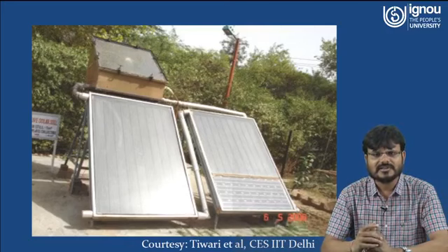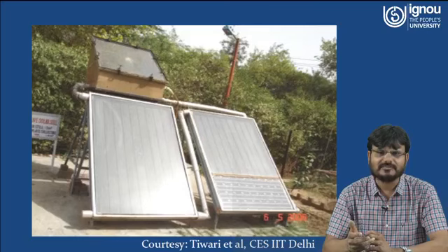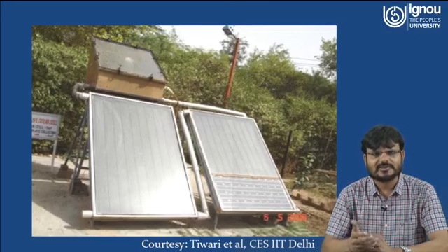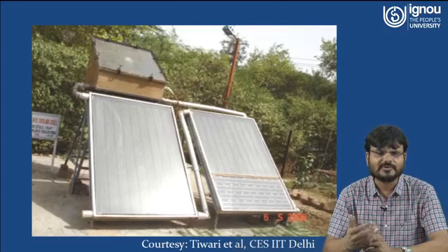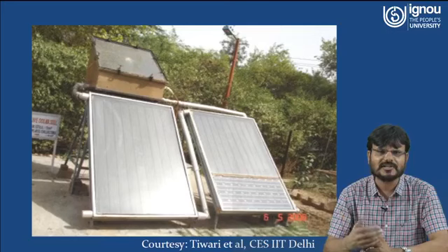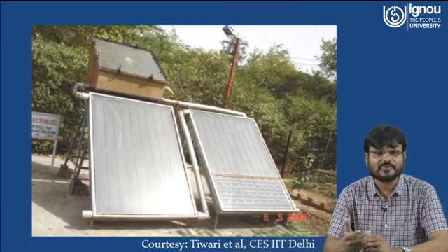Here you can see in the first chamber, below the chamber there is a transparent PV module which is used to operate the DC pump, which will force the water inside of the hot water collector, and this hot water will be transferred to the solar distill. So it will increase the temperature of the evaporative water. So more evaporation will occur. If more evaporation occurs, this water will reach the glass cover of the solar distillation. It will be condensed. That means you can collect more pure water at the outlet from the solar distillation.